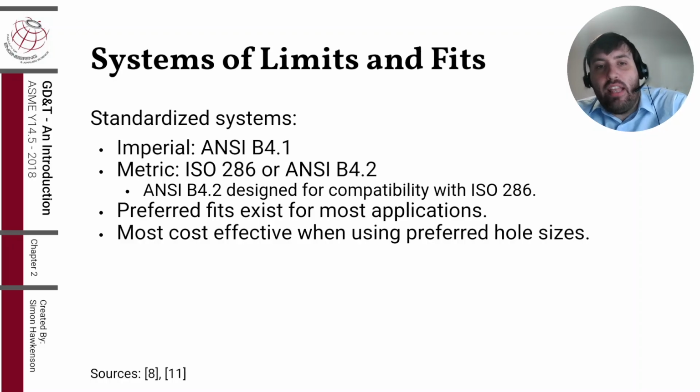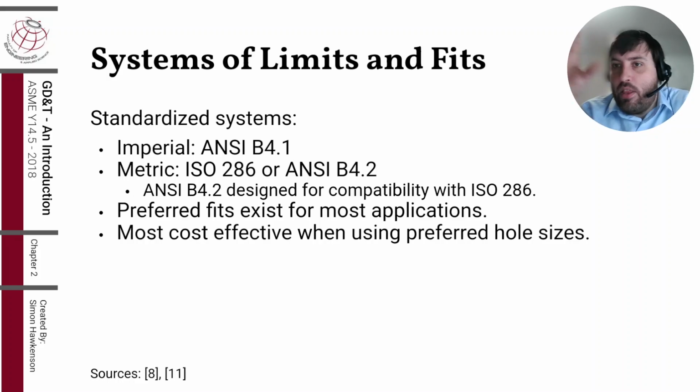So if you can, it's usually best to select from a standard list of fits based on your application. That's why you're using the system in the first place. And similarly, if you're buying a part, they'll often specify what fit that part is supposed to work in. So like if you buy a bearing, they'll often say your internal feature, your hole, has to be to this particular fit.